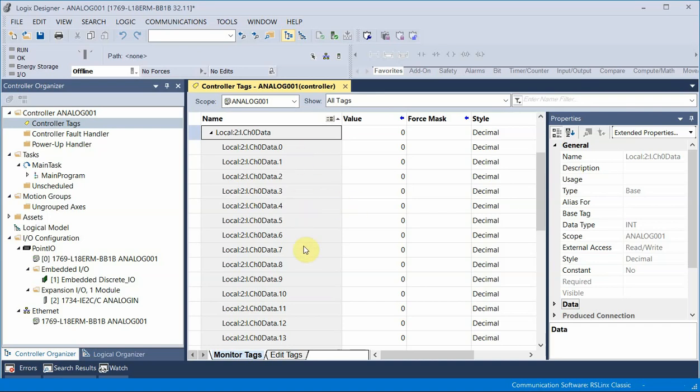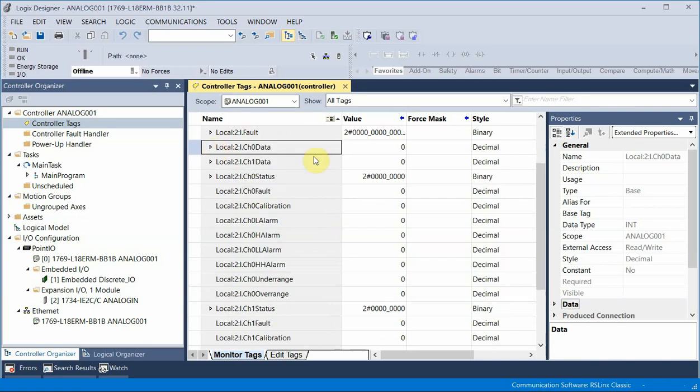These are little things that you want to check on. Also, since that's a 16-bit word, that's going to be a single integer, just a regular INT, not a double integer. So it's not a 32-bit value. That's important if we start to do messaging with the data coming off the analog card. We have to match the data type with the data that's coming off the card. But that's a kind of minor concern at this point. So far it looks good.